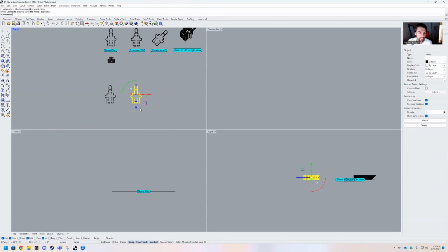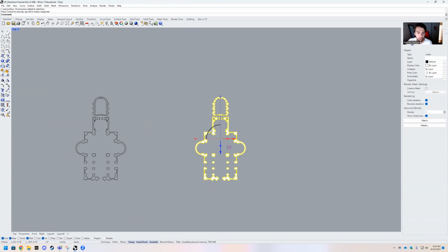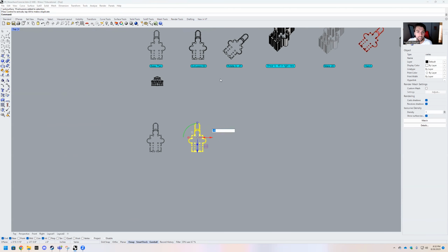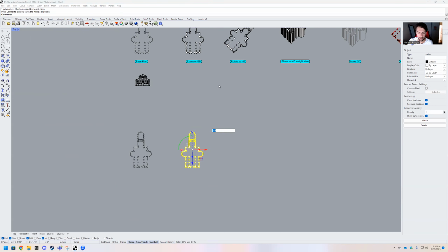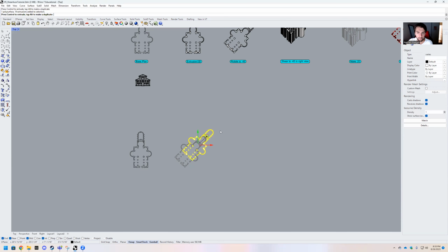Well, what I can do is take this and, using our gumball in top view, I can rotate -45, right? When I click this rotate button, I typed -45 in there and clicked enter and it rotates it. Now, what makes it negative is these little arrows that point around the gumball. Negative takes it the opposite direction that those arrows are pointing. Okay, so we've rotated this.